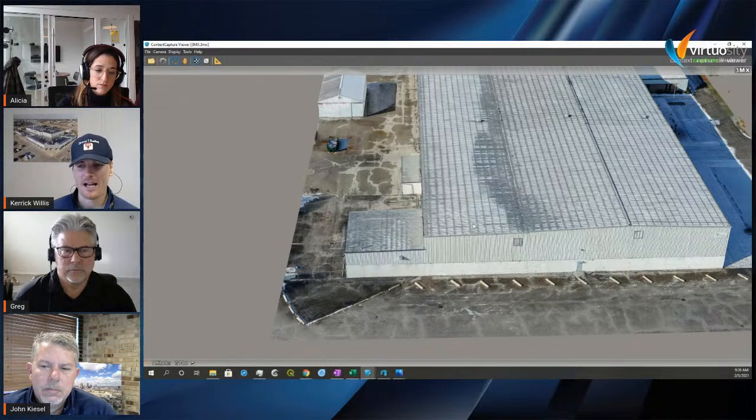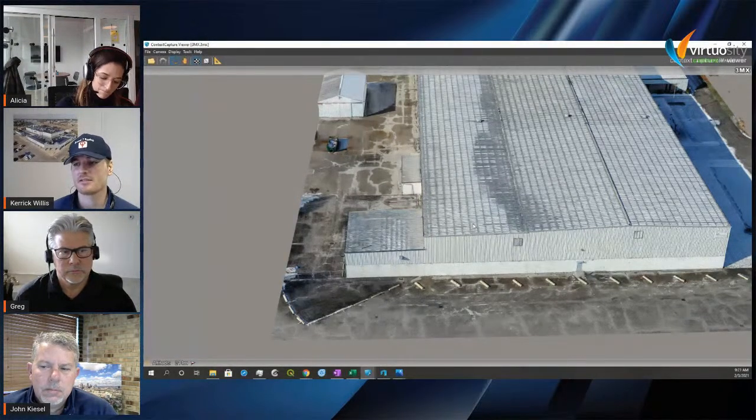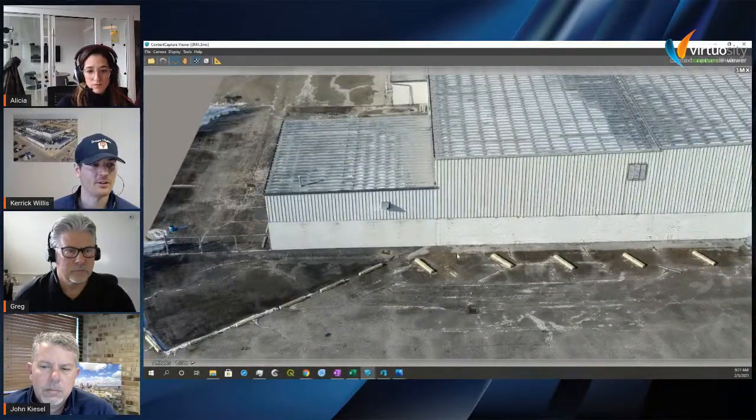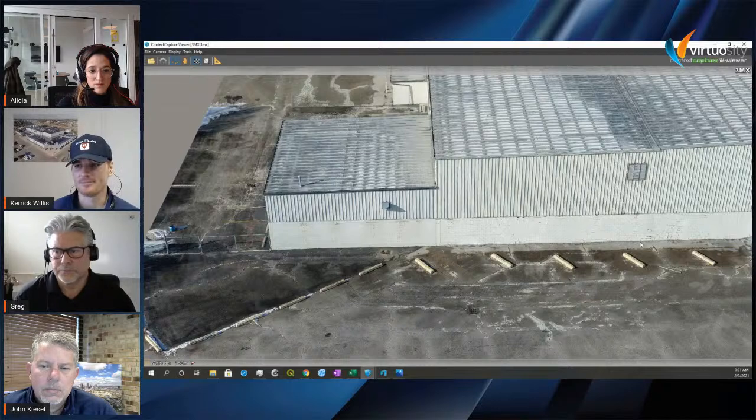So I'm not trying to hit that guaranteed spot, and that's where I was saying there could be some errors if you pull into Google Earth. It could be feet, all based on those GPS errors. Primarily, it's for viewing and measuring, and when you input scale constraints, going into normally at least the vertical and an X and Y down the building. On this one, I pulled it down the front edge of the building and then across some blocks sideways and then across the front of the building to ensure it's the right size and measurement.